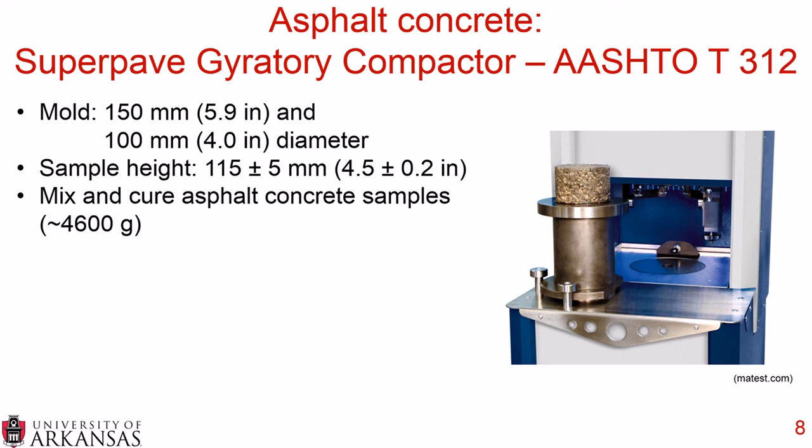The sample height, we're targeting 110 to 120 millimeters, which is about 4.5 inches. And in order to get this sample, we mix and cure our asphalt concrete samples, and we're aiming for approximately 4,600 grams.